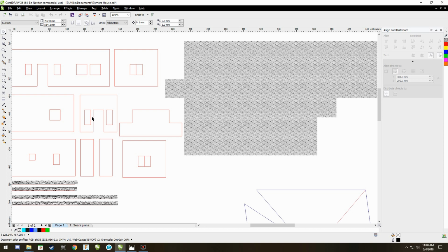When I send the drawings to the laser, it doesn't understand layers, but it does understand different colors. So when I send the drawing to the laser, I will assign different power settings to the laser, speed and how much power is going to the laser, and based on the material I'm working with, it'll either cut through or not cut through. Just as a practicality, usually what I do, not always, because I'm going to show you some drawings where that's not the case, red is my primary cut-through color. Now we'll get to these grays here in just a minute, but I want to just talk about the colors.